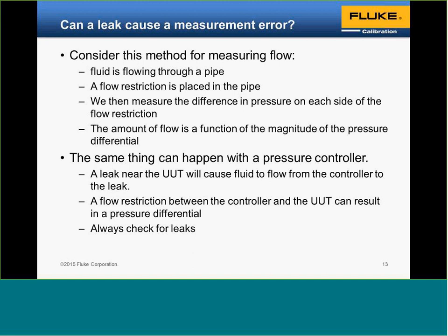Start your calibration process off with a leak check, where you take the unit up to a low pressure for a bit to eliminate the temperature effects, and look for a pressure drop. A pressure drop will signify a leak.